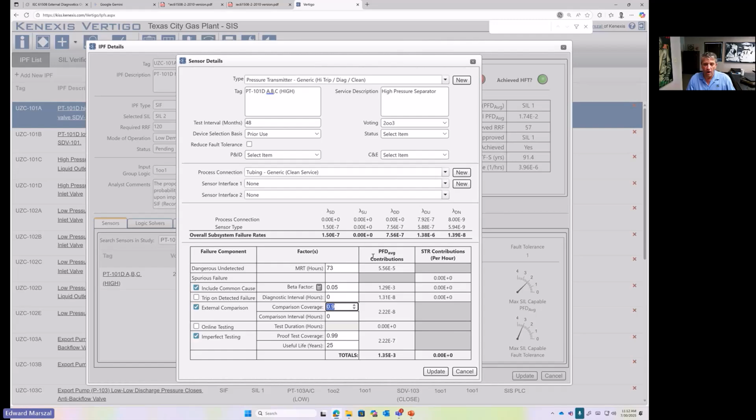you need to understand what a comparison between those two signals actually means in terms of whether or not you're stuck in place or whether or not you've drifted. Honestly, if you convert everything to engineering units, then the comparison of engineering units should take all those vagaries into account. But honestly, I haven't thought that through and done the math, so don't quote me on that as absolutely true. It feels like it would be true, but I would need to crunch through the numbers and run some example cases to confirm that. But yeah, that's a good point. If 12 milliamps on transmitter A and 12 milliamps on transmitter B mean different things, it's really hard to make a comparison.